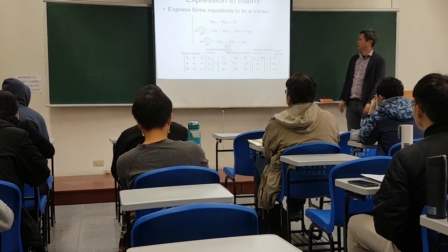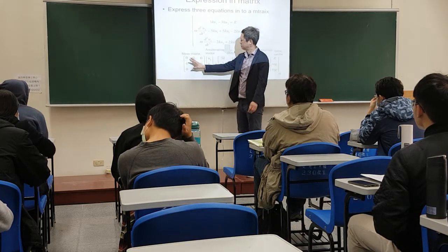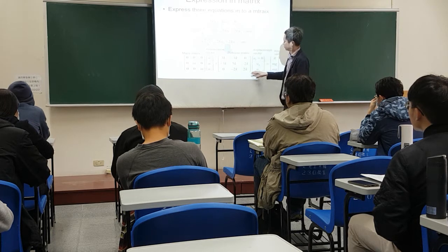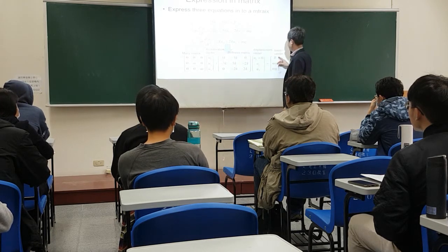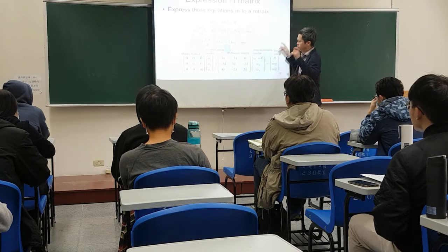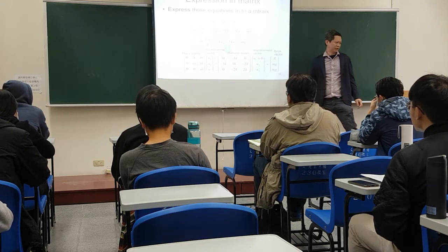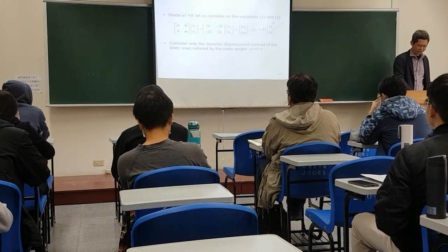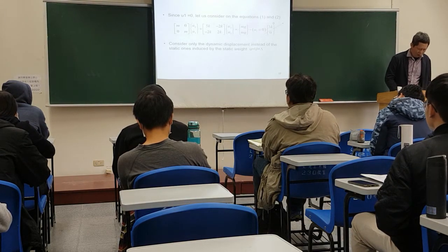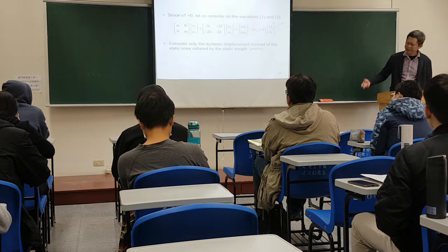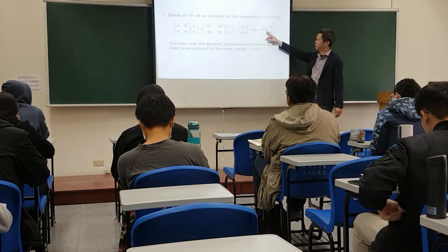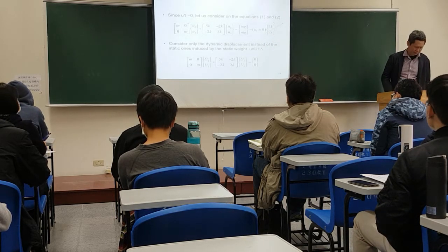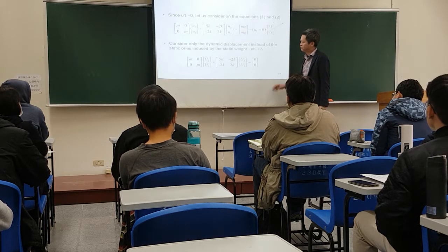Then you're going to rewrite them in such a way that you have acceleration term times mass matrix, displacement term times the stiffness matrix. They all sum up to become the so-called reaction force or real external forces. So this one excludes the harmonic forces yet. But later, if you are substituting in the known displacement, then you reduce the 3 equations into 2 equations. And in the absence of the weight,